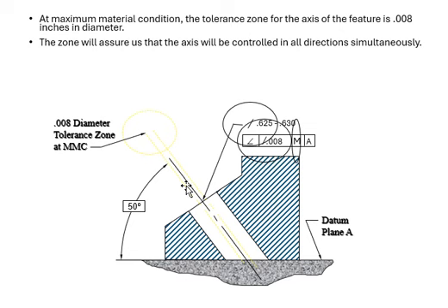So you know that we're talking about a diameter of that tolerance zone, because the geometry of the tolerance zone is a cylinder. We're dealing with a diameter measured from the axis, all around to the tolerance zone limits, which is 0.008. So be very careful what type of tolerance zone you are getting. If you see the little circle like that, not just two parallel planes, you know that you're dealing with 360 degrees all around, so it has to be a diameter.